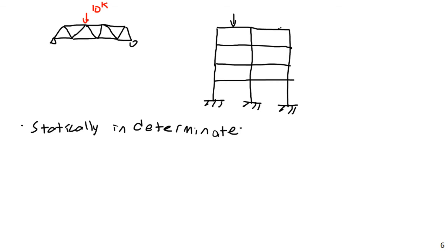A good example would be continuous spans, such as a very long highway bridge beam that goes between multiple supports. That is an example of a more indeterminate type of system that generally produces higher efficiency. But statically indeterminate systems, there may be some exceptions, typically have greater redundancy.